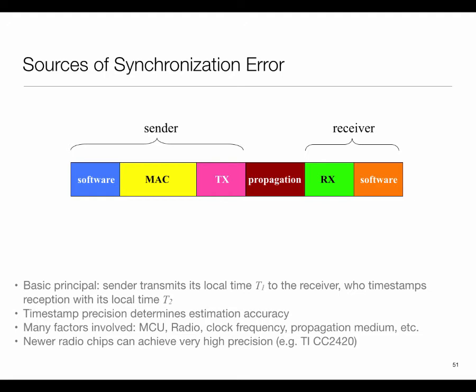These are all things one can study and characterize. I'll have some plots showing that the radios do have significant variation in the delay for all these factors, because radios have state machines inside them. Also, sometimes the algorithms are data dependent. If the packet has a series of zeros, they may behave differently than if the packet has a random value. Depending upon the channel condition, things may vary, like more coding and decoding needs to be done. So things can get tricky. Modern radios and Ethernets change the rate dynamically depending upon channel conditions. So there are complications, no doubt.